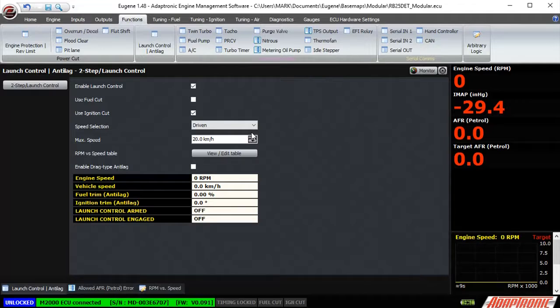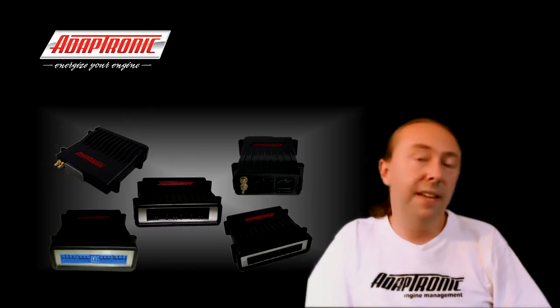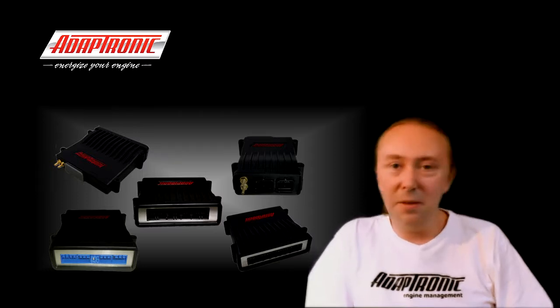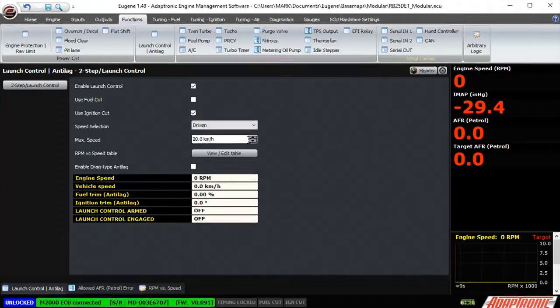It should be fairly obvious that once the clutch is fully engaged, the RPM and the wheel speed are closely linked anyway. So being able to do a rev limit based on speed doesn't really make much sense. As an example, if you've increased the RPM limit at the higher road speed, then if you launch too high in RPM, the road speed's going to be high because you're wheel spinning too much. So that won't actually help you in that condition. Now the maximum speed is the next setting, and that's the road speed above which the launch control and anti-lag function won't operate at all.